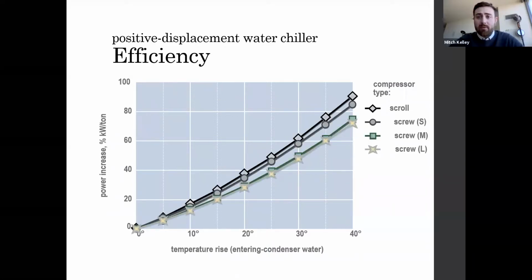In addition to the capacity reduction, the power necessary to provide the compressor lift increases. Although the chiller can operate in heat recovery mode, one should analyze whether the additional power required and the reduction in capacity warrant the benefit. This slide shows generically how two positive displacement compressor technologies react to elevating condenser temperatures and pressures. Because both power and capacity are changing, the power draw is shown in units of kW per ton.